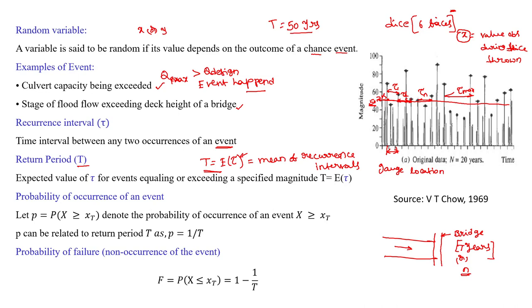Okay, so you must remember these two points. One is the average, another is at least. It means that at least once it will occur. It does not mean that it occurs only once; it can occur 2 times, 4 times, 5 times. This is a common confusion we have. And one more confusion: suppose in 1947 this Q event happened. When we say this is a 50-year event, people tend to imagine that 1947 plus 50, maybe 1997, after 50 years only there will be another event. This is wrong. This is also a wrong perception.